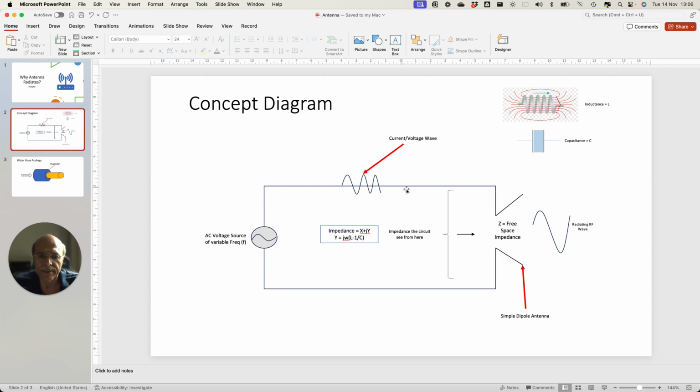So in this diagram, you see there is an open end, meaning the circuit is not completing, which will look quite strange to you because normally in a circuit diagram, the circuit should complete, meaning it should go from one end and return back on the other end. But there is a gap here. This gap is where the antenna attaches. This is the convention which every technology or every kind of implementation will follow. There will be a gap, and instead of terminating from this point to this point, it will terminate into free space.